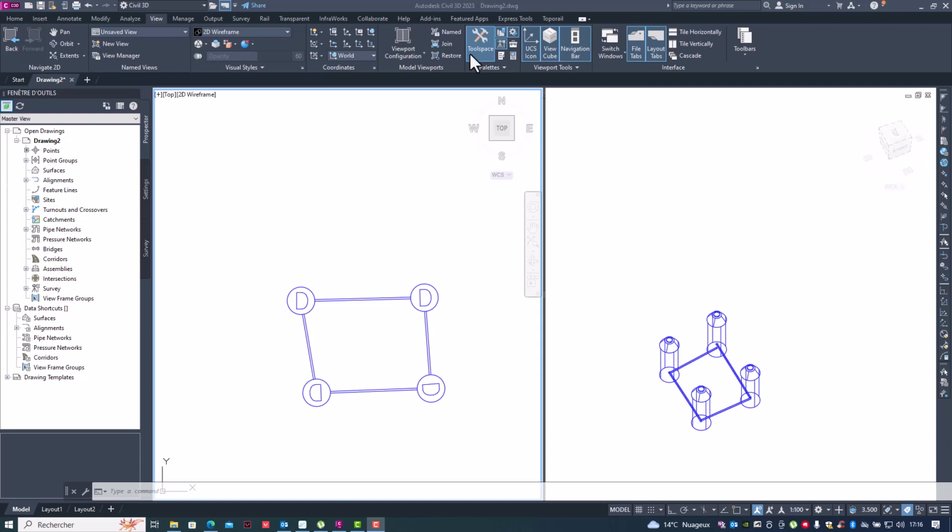In today's video, I will be showing how to export with IFC 4.3 in Civil 3D, and we are going to compare it to the usual way of IFC exports. The usual way of IFC exports in Civil 3D is to convert objects into 3D solids and then export them. The problem with this way is that the objects exported are going to lose their assigned properties.